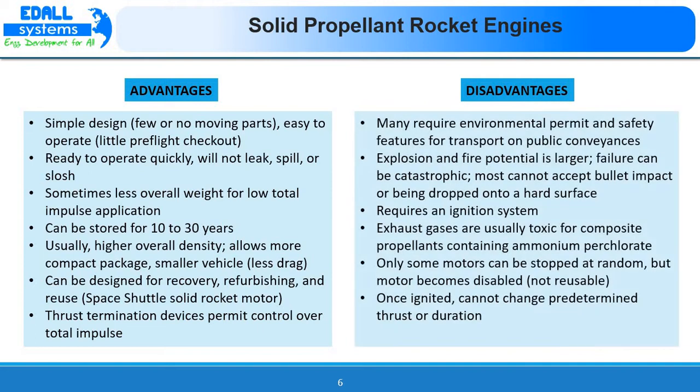Then the disadvantages for solid propellant rocket engines are that many require environmental permits and safety features for transport on public conveyances. Because we carry such explosive chemical fuel and oxidizer with us, which is contained in the grain, they are very harmful for the environment. Explosion and fire potential is larger, and failure can be catastrophic. Most cannot accept bullet impact or being dropped onto a hard surface. The elements which compose the propellant grain are explosive and the failure can be very catastrophic.